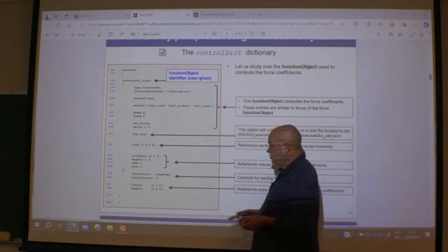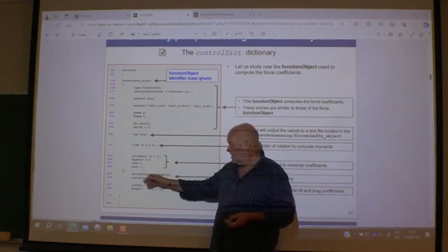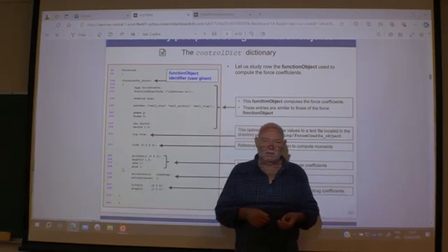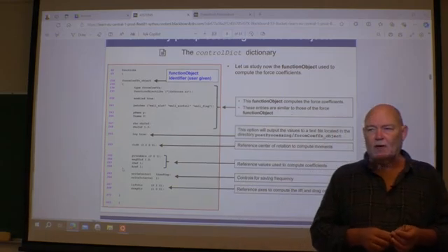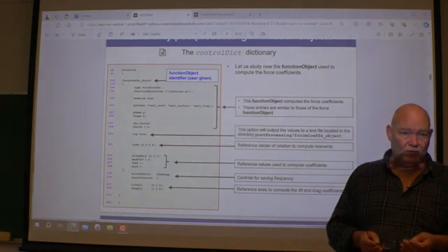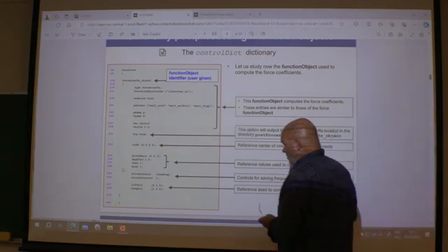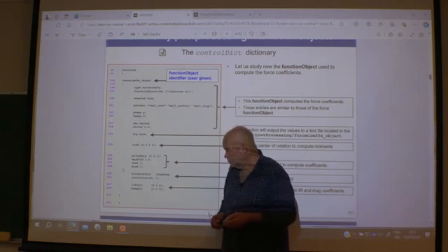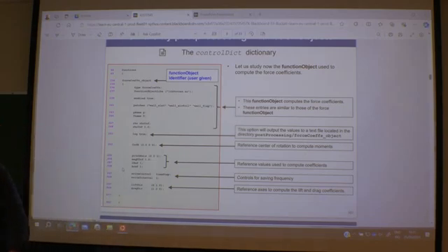And here you can choose what kind of scales you want. I would say it's a good idea just to use 1, 1, 1. And then afterwards, once you have received the numbers, you can scale with your own parameters. So your own area, your own reference velocity, whatever. So I would suggest 1, 1, 1, just to do it easy. But you have to specify these numbers.